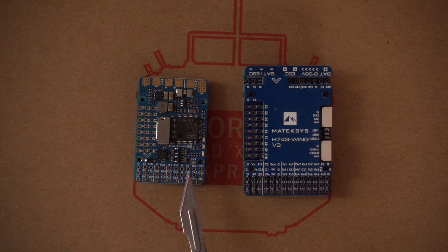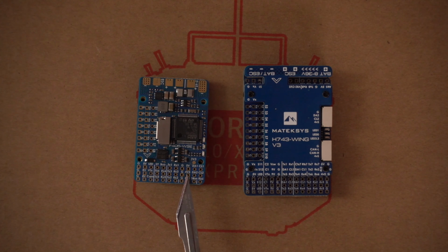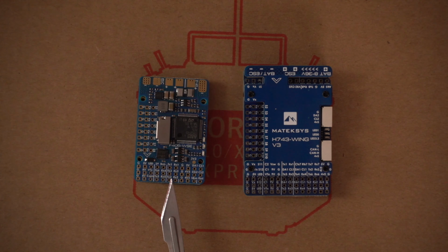There's a couple of differences between this one at the top, which is TX and RX1. So that would be UART1 on the ports page. This one has a 5 volt, so that is getting it from the 5 volt rail. The TX3, RX3, ground and 4V5 is using 4.5 volts when it's connected to USB, but when it's connected to the battery it will be using 5 volts. So these two bottom ones here will actually work when you've got your USB cable connected. The 5 volt ones won't. So that's why it's a good idea to put the receiver on one of these 4.5 volt ones and the GPS on the other one. It just makes things much easier to set up.